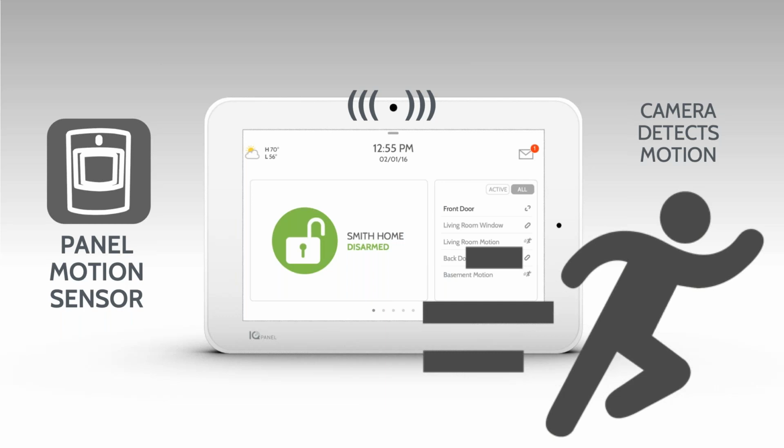On top of that, if you have the panel motion on, it allows you to do a couple other things. Peek in next motion, and also we talked about the Bluetooth disarming. And people said, well, if you use Bluetooth disarming, do you get that disarm photo? Well, if you have the panel motion sensor turned on, then the next motion it sees, it's going to take a picture for you. So whether you're using the Bluetooth disarming, if somebody uses their alarm.com app, or if they have a key fob, it'll still take a disarm photo through this panel motion sensor.